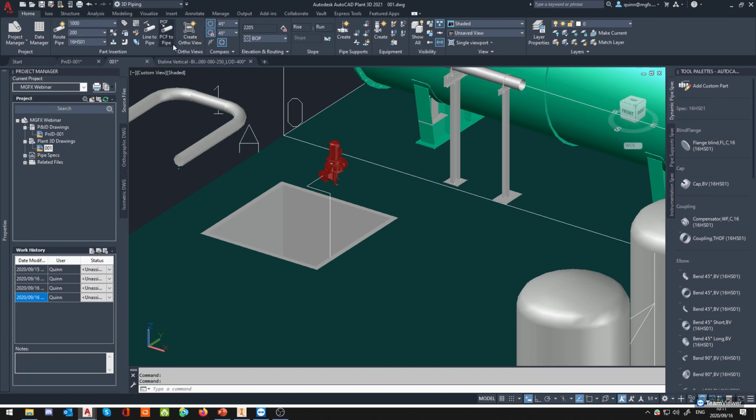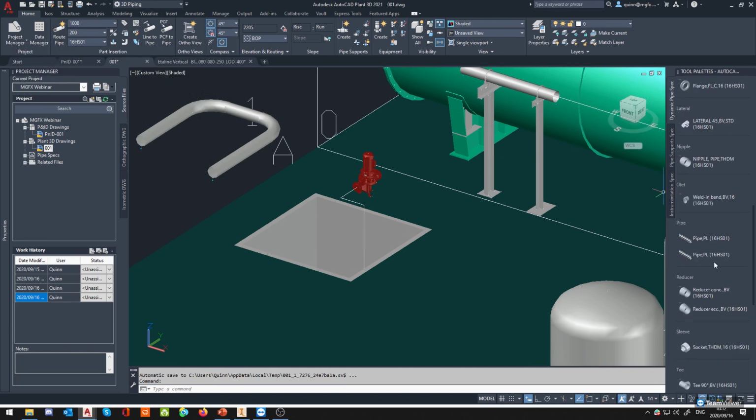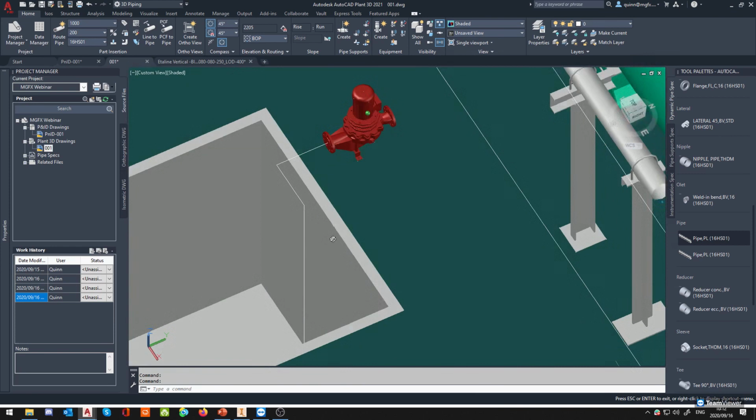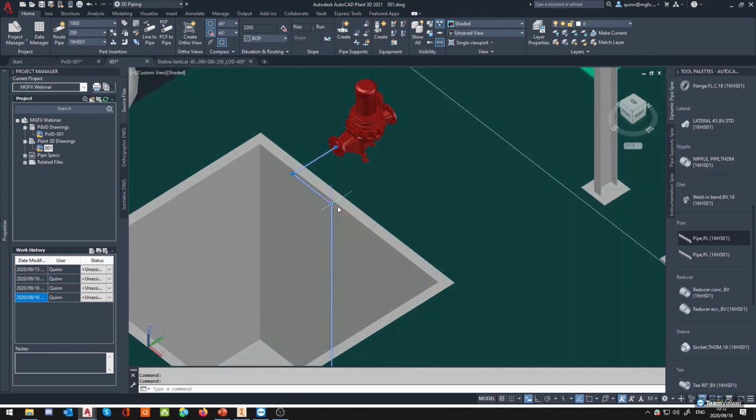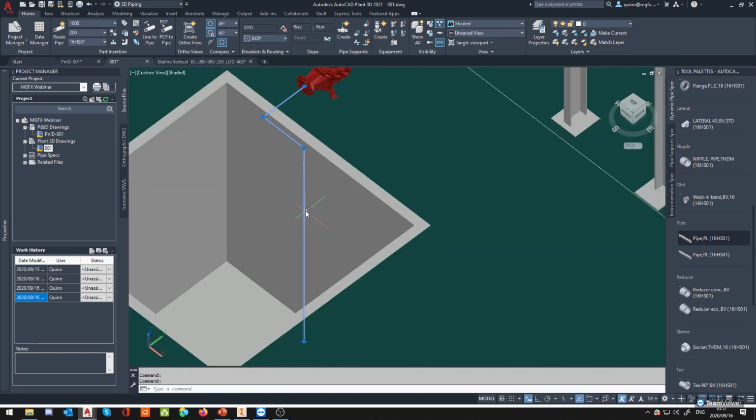Otherwise, looking here more at the part insertion. A lot of the guys will, like I said, use it just as a plain routing of pipe, or otherwise routing pipe in our tool palette on the right over there. Both are fine, but you can make it a little bit more interesting. For instance, if you look over here, I have got a polyline that's routed around. If I select it, you can see it's actually a 3D polyline.